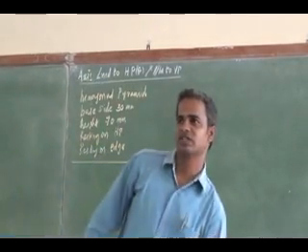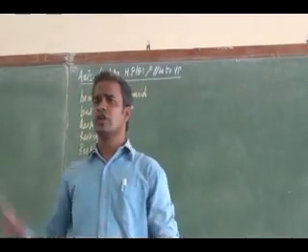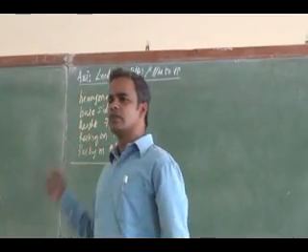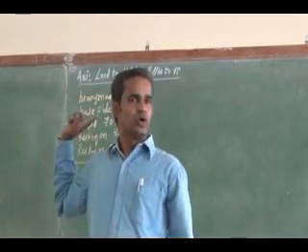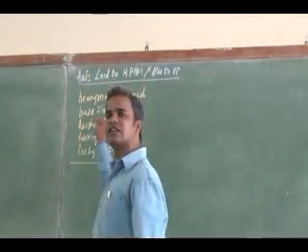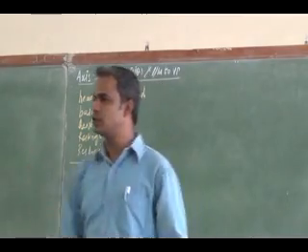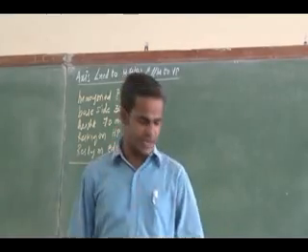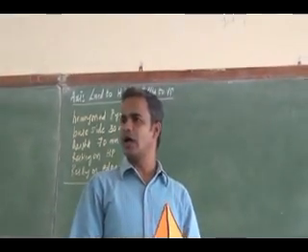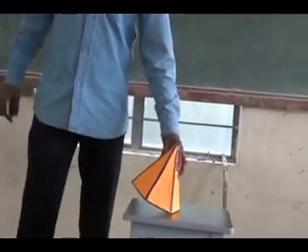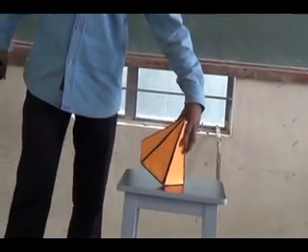See here, I will just explain. Is any axis inclination given in this? There is no axis inclination at all. Then how do we find out whether it is inclined to HP or inclined to VP? See the problem: it is resting with the base edge. I have a hexagonal pyramid resting with one of its base edges like this. So it can rest like this in any orientation.